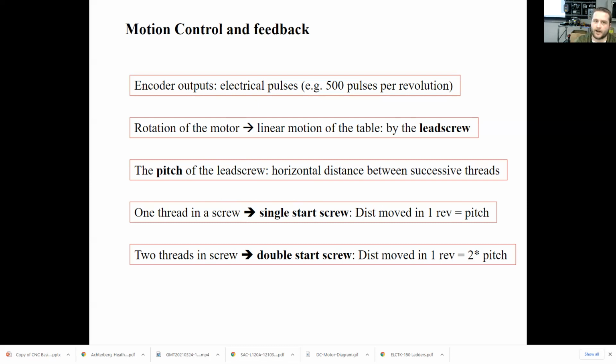And the reason that we had this guy come up here to help us with those machines is because I could get everything to work okay, but the parameters are so jacked up. Those things are 20 years old. And people have screwed with the parameters on there so much that if you tell it to move 2 inches, or if you jog it 2 inches, it'll tell you on the screen that you moved 160 feet. So you actually have to measure the pitch of the screw and input that as a parameter, all this stuff that I don't really know how to do, so that what's showing up on the screen and what you're doing on the piece of equipment is jiving. Anyway.